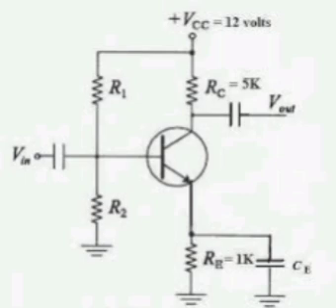One scale division equals 5 by 100, equals 50 millivolts. Minimum voltage that can be read on the voltmeter equals 1/5 into 50, that equals 10 millivolts. Resolution of the instrument equals 10 into 1/800, that equals 0.0125 mm.